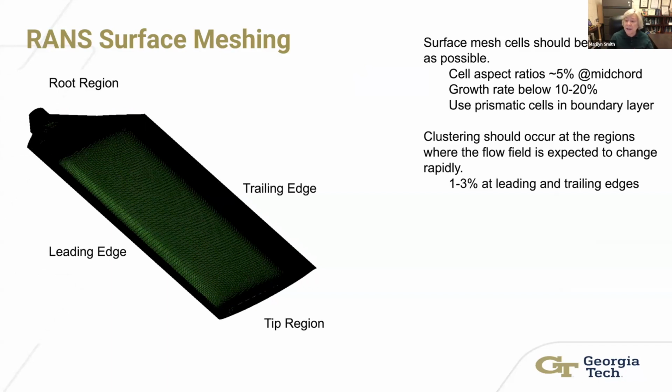So here are some guidelines. You want to, in general, make sure that you don't have your growth so high that it's impacting your simulation. Remember, you're solving PDEs inside of your simulation. If you're running an unstructured mesh, hopefully it's sophisticated enough to use mixed elements. You want to use quadrilaterals, not tets, near the surface.